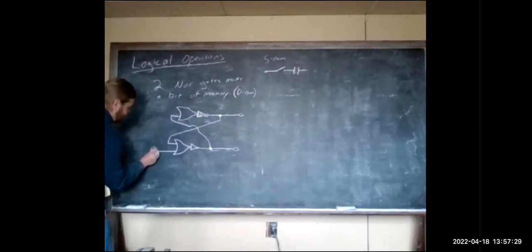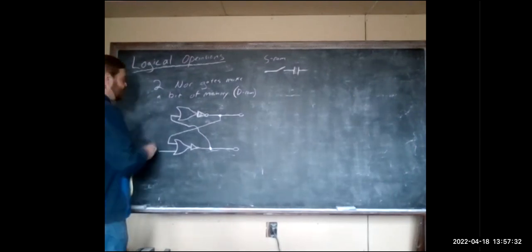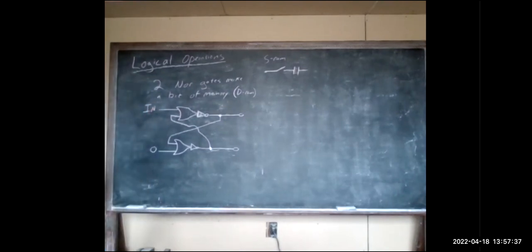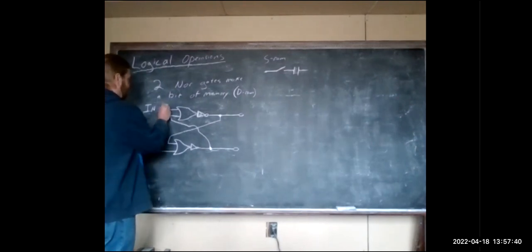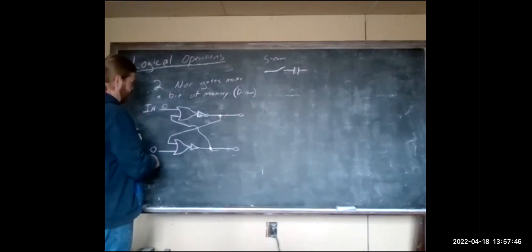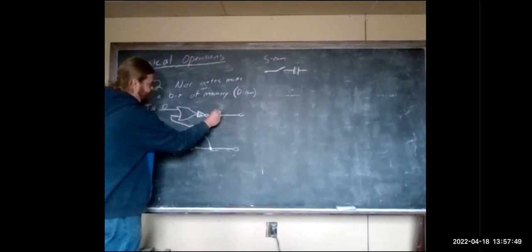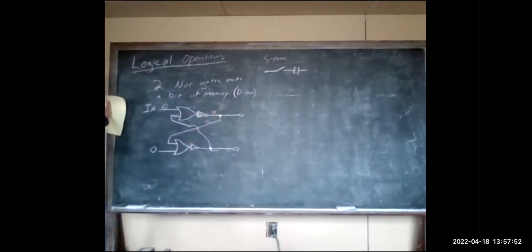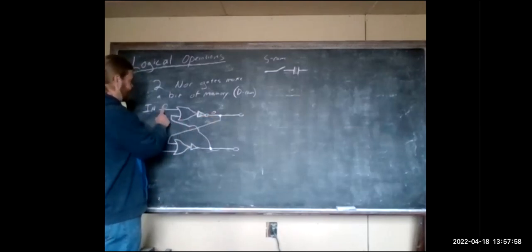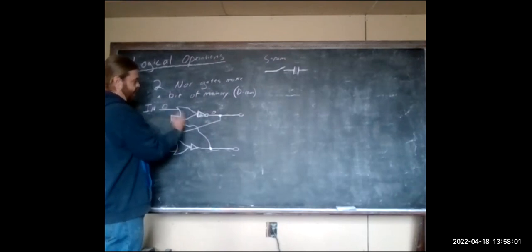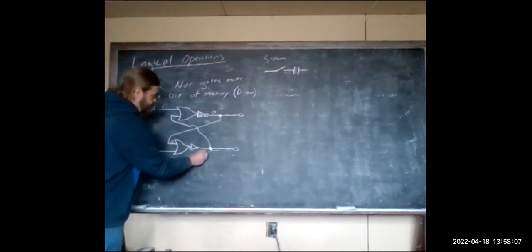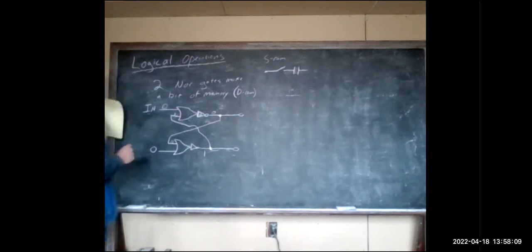Then we have another one that's just always tied to 0, just always stays as a 0. And then we have our actual input. So first, everything's going to have zeros, right? I'll put a 0 here. Which makes, well, ultimately a 0 is going to come out of there. This has a 1 on it. We'll get there in a second. 0 and 1, NOR would give us a 0, which feeds a 0 in here. We get a 1 out here, which comes back up here.